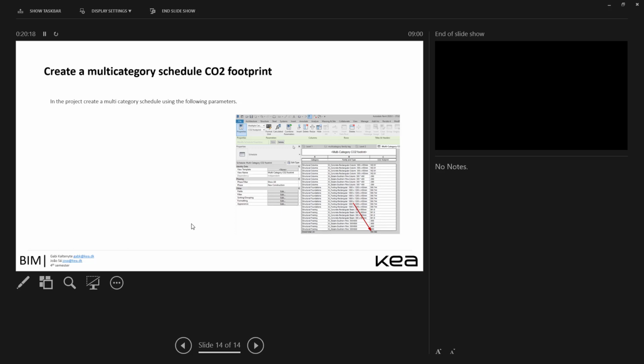What we have to do is use the specific CO2 footprint per element, per unit of element, in this case 1 meter of beam, right? But before that, we have to decompose it and calculate how much is the concrete, how much is the wood, join both together, and that's my new number that I shoot into Revit for this specific element.